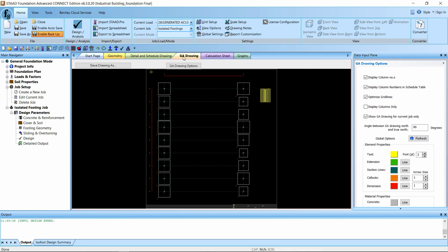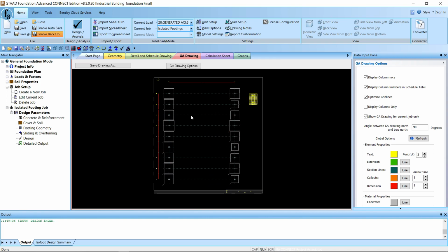Okay, so these are the foundations design. Since the reverse loading conditions for wind etc. is not considered, that's why we can see the difference in sizes on left and right side. We can select the largest value. We can fine tune this one, no problem. The one thing which I wanted to check, that there should not be any overlapping, and of course these foundations are isolated foundations, they are not overlapping, so we can follow this design.